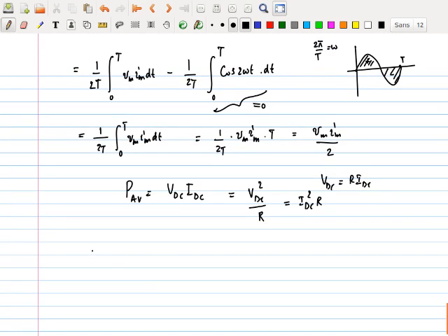So I would get, let me call them, VRMS and IRMS. Both of them are DC values, so it's like V times I. If I equate an equivalent DC circuit which has signal power VRMS times IRMS to this AC one, which is Vm times Im over 2,